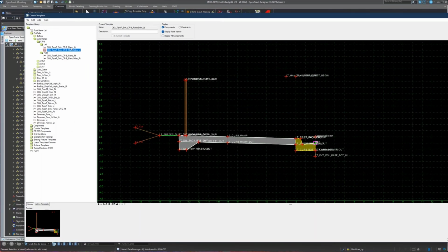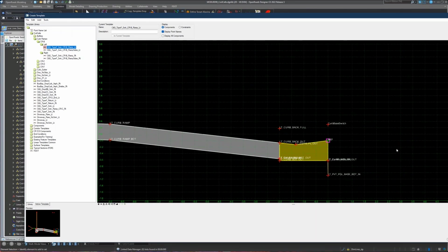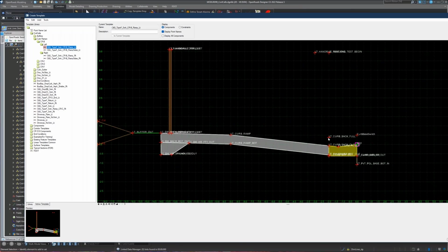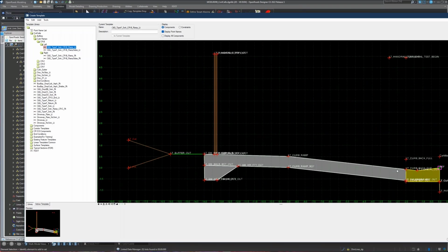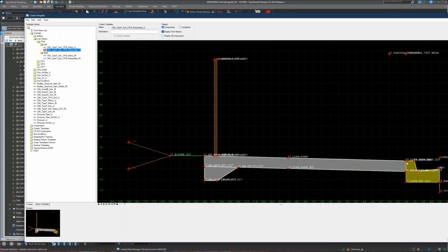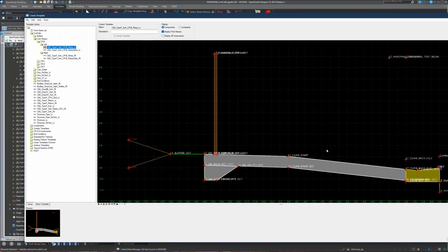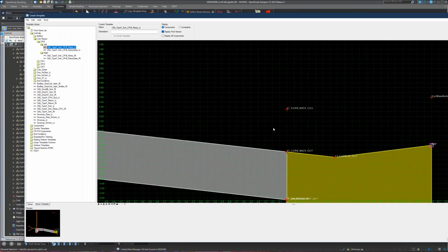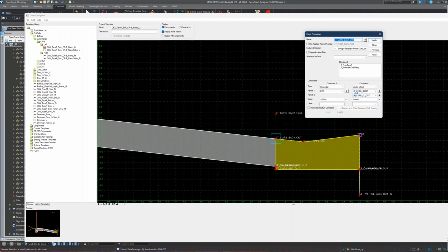And then the other ramp is only slightly different, where this is just where I've already got the curb drop down. So you can see I made a direct copy of this. I just made a few modifications. So I got rid of the curb face out point because I don't need that. And then I adjusted this point right here to still be 2 feet from here, but now it's on the vector offset of the ramp.